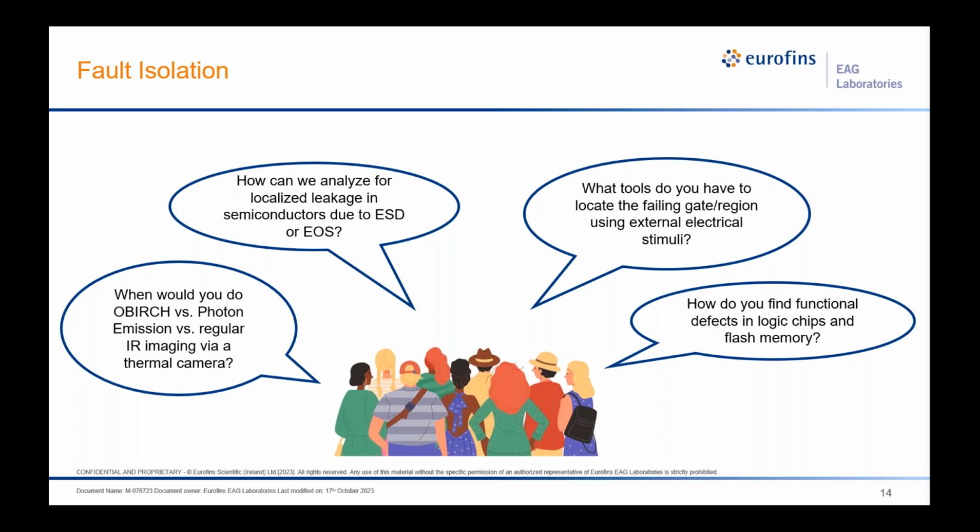The differences between these three techniques are spatial resolution, detection sensitivity, and many other factors. OBIRCH uses a laser, so if we can get a response from OBIRCH, the spatial resolution is great, and the contrast of imaging is the best. The highest magnification air gap lens is 100x, and you could use a solid immersion lens.